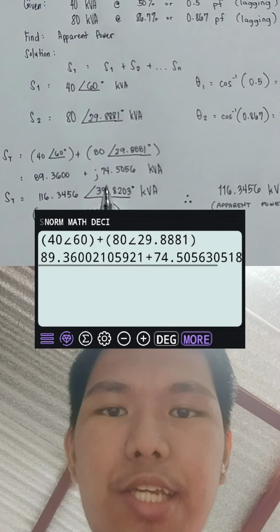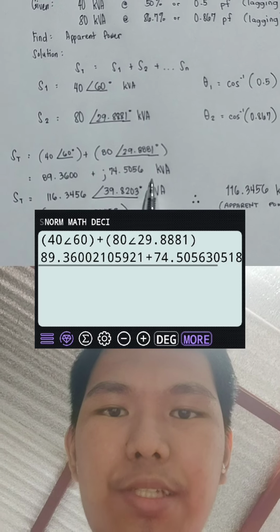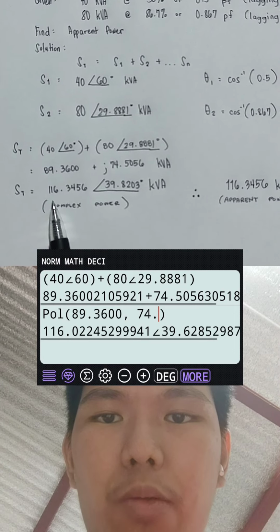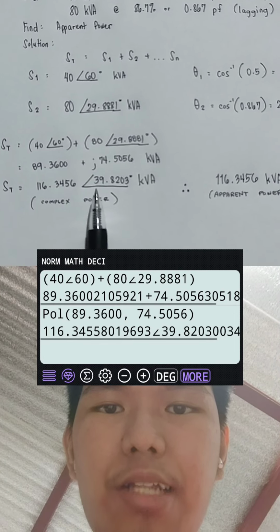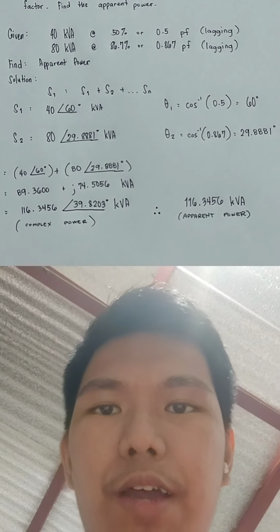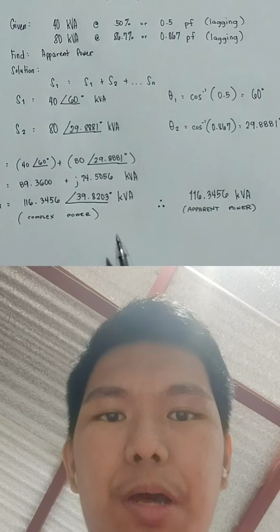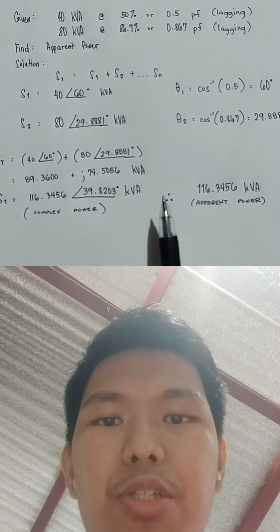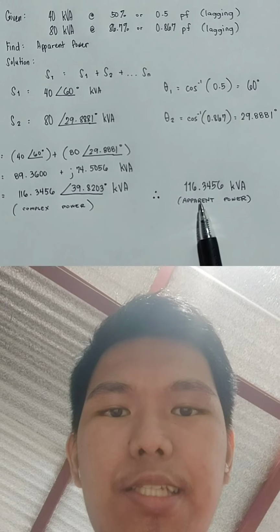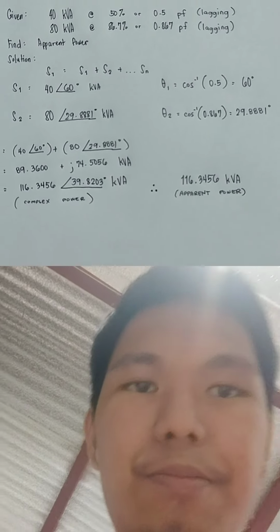Its polar form is 116.3456 angle 39.8203 degrees kVA. Since we are finding the apparent power, it is only the magnitude of the complex power. Since this is the magnitude of the complex power, it is the apparent power. Now, our apparent power is 116.3456 kVA.